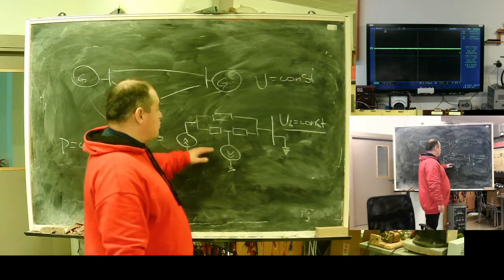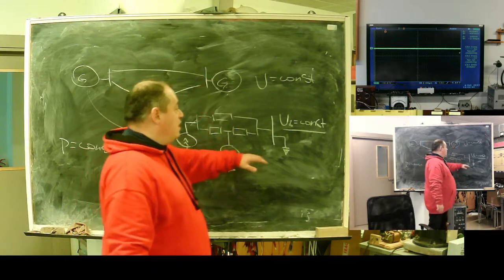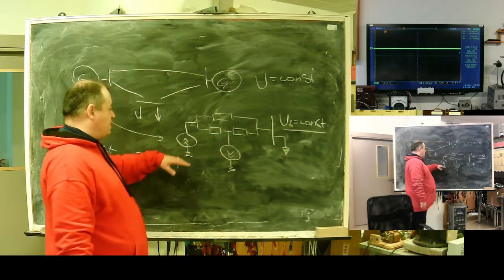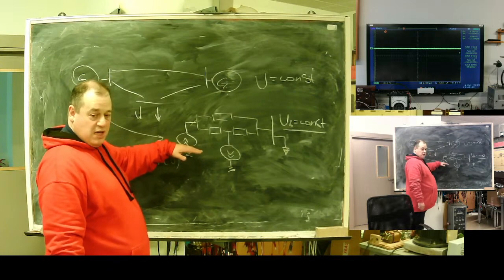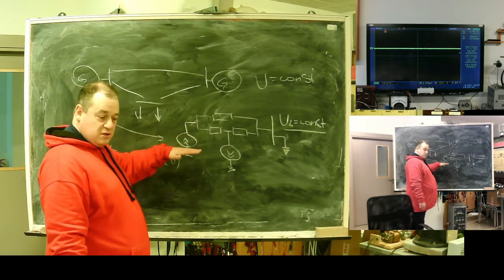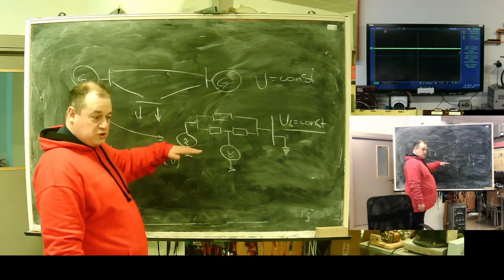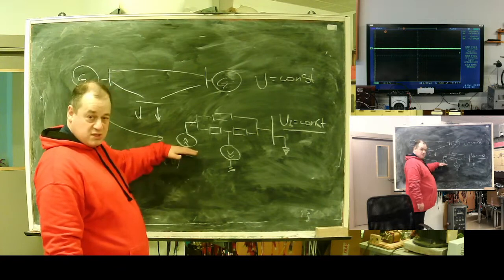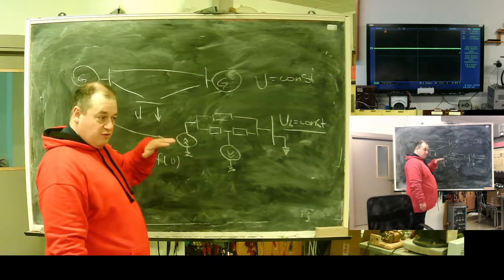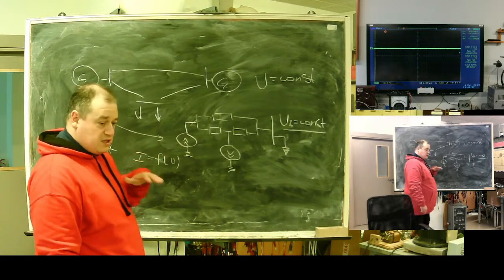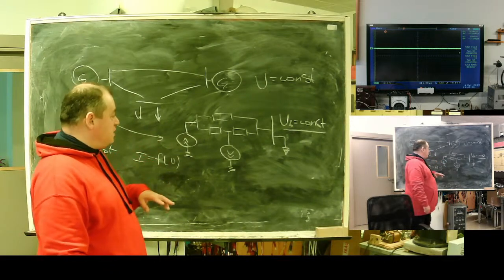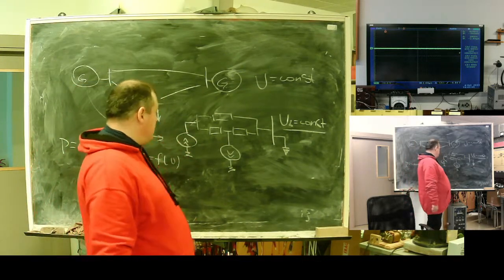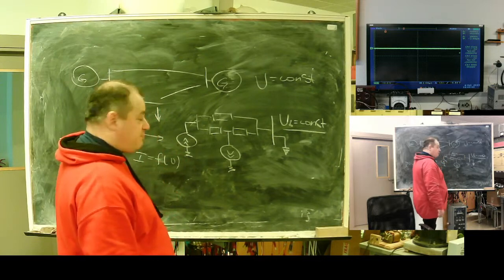So one station, slack bus, fixed voltage. Other stations are reflected by current sources. It's usual. If needed, you can also use EMF if there is a voltage strategy. But the usual strategy is power, and a current source is better. If two or more stations are keeping voltage, this means there will be not a current source but EMF. But it's quite a rare thing. Usually one by voltage, others by power.